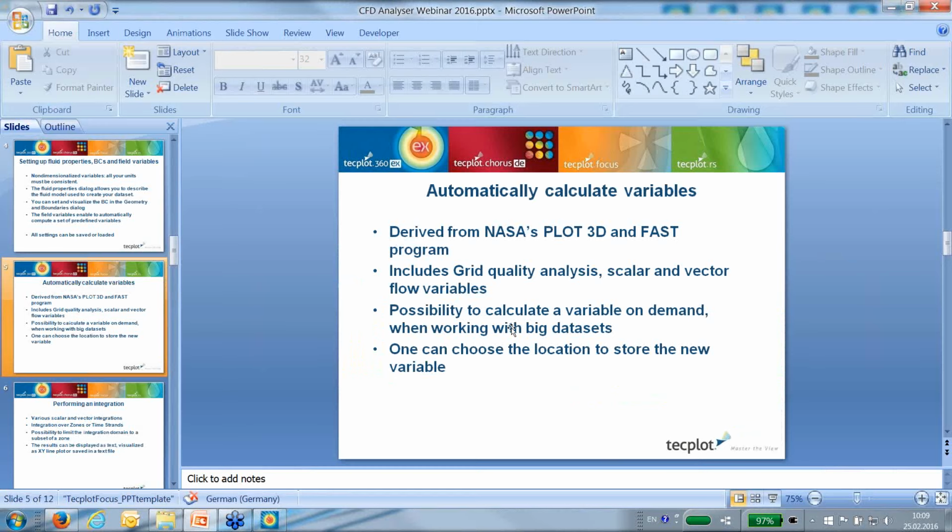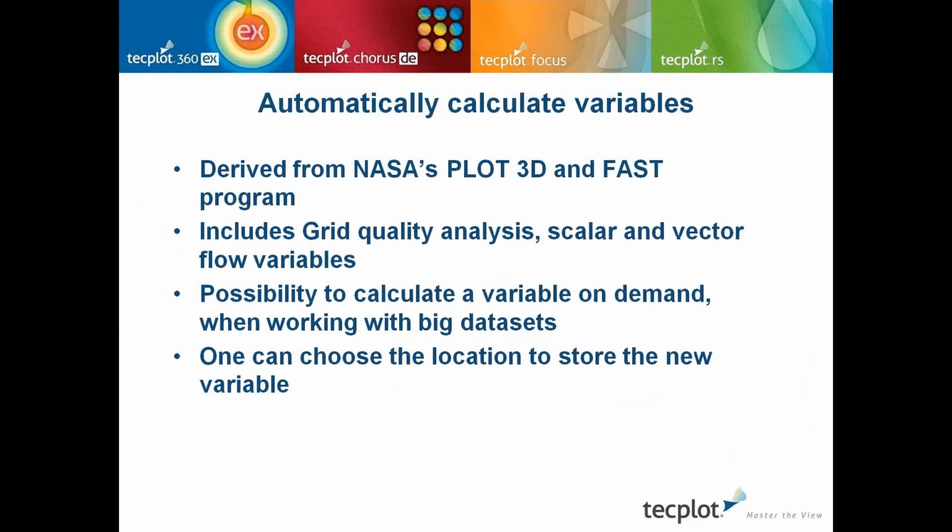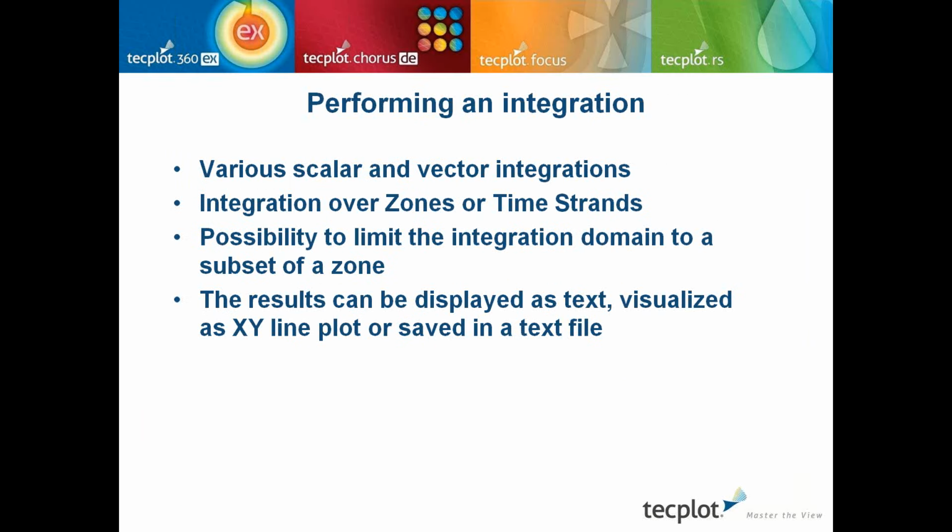Okay. So now we'll speak about how to perform an integration within Tecplot. You have numerous scalar or vector integrations available, and you can integrate over zone or time strand. So basically a time strand is a group of zones that correspond to one object, and that object can exist in many time steps, for example.